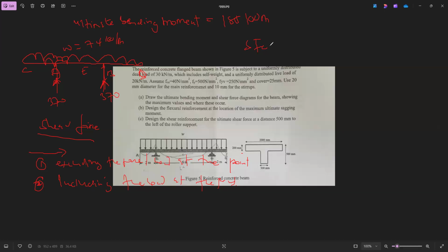Okay, so shear force at C, first excluding everything, is 0. You see, at C we don't have any load or any support, so you will take only one shear force value.